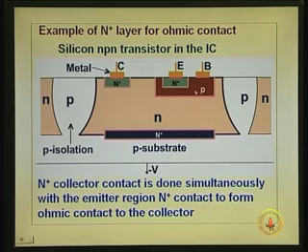But what about this n region that is base? If a P there will be n, you must put an n plus region, that has got to be a separate step. This is one of the difficulties when you want to make PNP transistors. In fact, if you carefully see, the PNP transistors are costlier than NPN because of that additional step of forming the n plus contact.